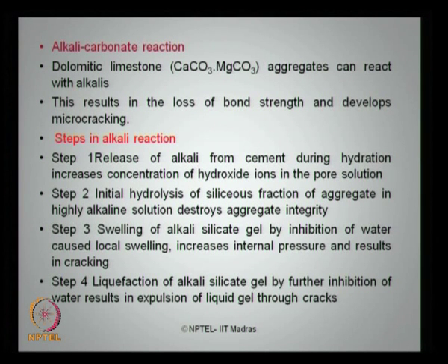As a first step, release of alkali from cement during hydration increases concentration of hydroxide ions in the pore solution. In the second step, initial hydrolysis of siliceous fraction of aggregate in highly alkaline solution destroys the aggregate integrity completely, followed by which swelling of alkali silicate gel by imbibition of water causes local swelling, increases internal pressure, and this results in cracking of concrete. As a last step, liquefaction of alkali silicate gel takes place by further elimination of water. This results in expulsion of liquid gel through cracks.